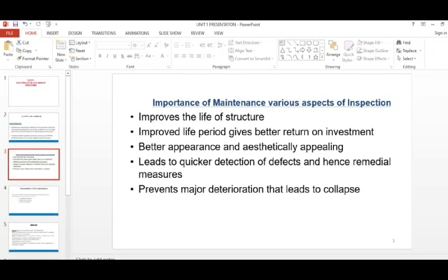Weekly maintenance routines generally cover electrical accessories, flushing sewer lines, and leakage of water lines. Monthly routine maintenance includes cleaning doors and windows, checking the septic tank and sewers, observing cracks in the elements, cleaning overhead tanks, and checking peeling plasters, dampness, or floor cracks. Yearly routine maintenance includes attending to small repairs and whitewashing, painting steel components exposed to weather, and checking displacement and remedial measures.